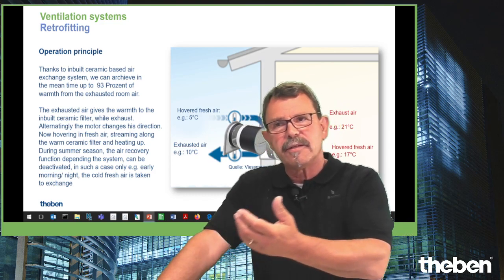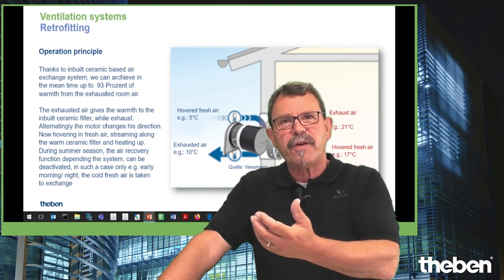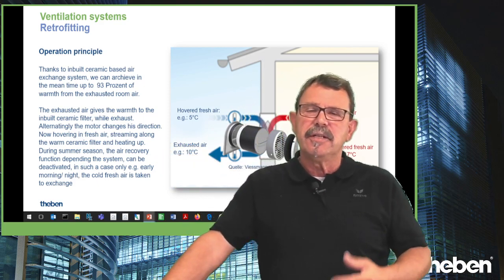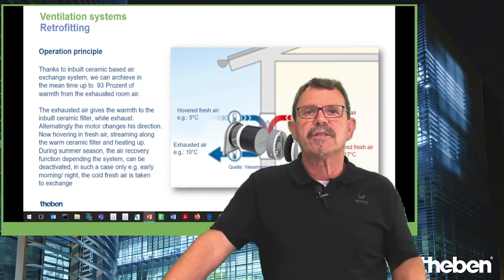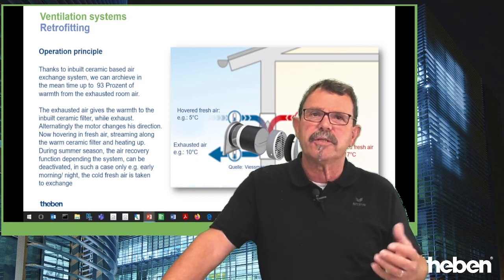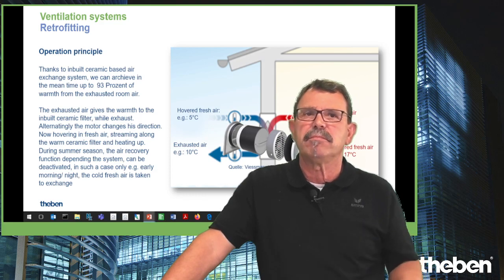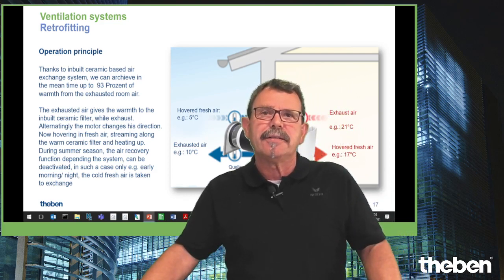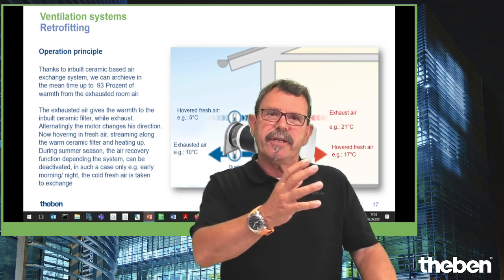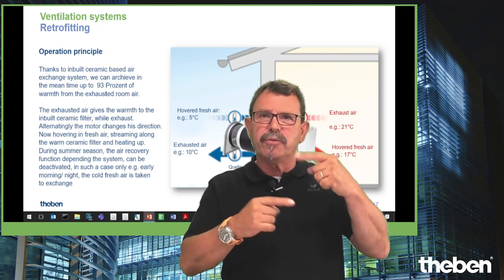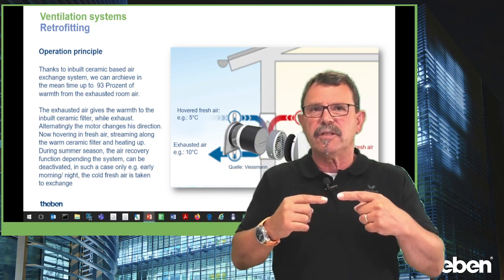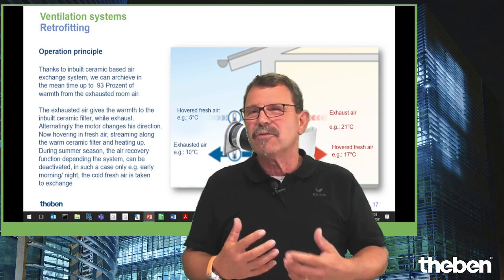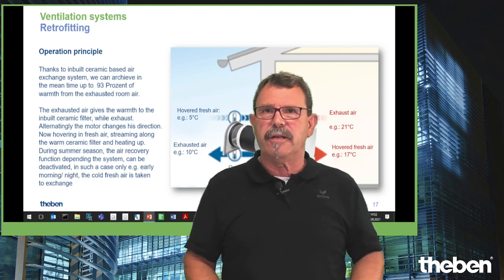Then, sequentially, the fan hoovers in the fresh air from the outside, streaming along this ceramic filter, which was heated up from the exhaled air. And so the fresh air coming in is heated up, so that means the gap between the temperature inside and the temperature outside is not big anymore. So it's a rather energy efficient solution.